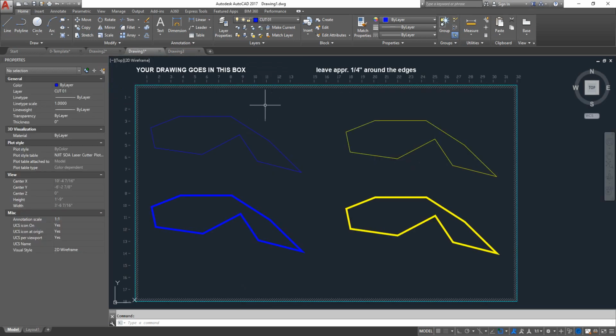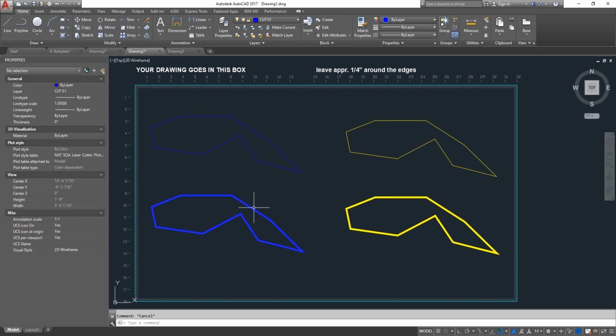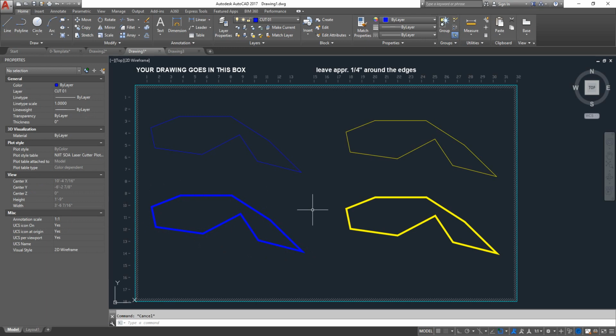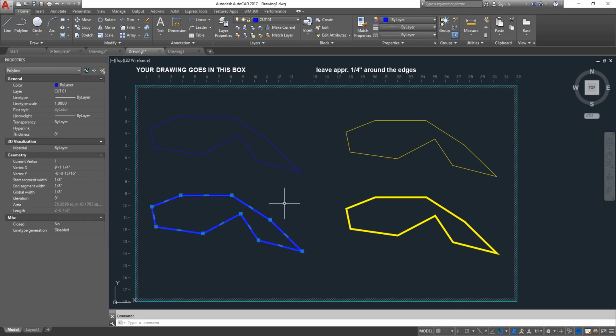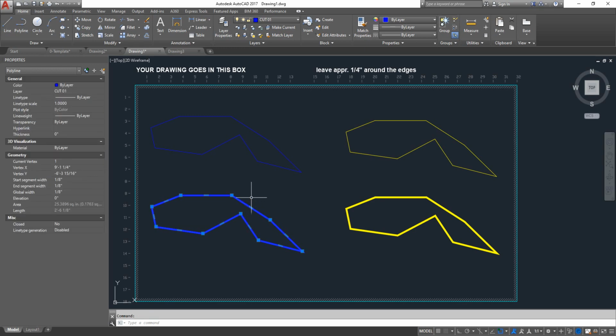So here we have, in the proper layers, this vector cut, right? And we have the same file, but it has a thickness to it. Now, if you sent this to the machines, they will run them and actually cut these files. So this vector cut would take about 15 to 20 seconds. This would actually engage into a raster cut mode and would take about 5 minutes to cut. Now, it's the same exact end product, but the time differential is huge. Plus, this would actually end up looking a bit more toasty.